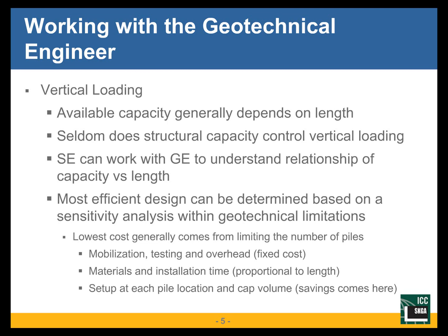We should realize that the cost in a pile foundation system comes from a number of different elements. First of all, you have the mobilization. That is, getting the pile contractor to the site, getting all their equipment there and set up. It's basically a fixed cost depending on how many rigs they're bringing to the site. And then you have the materials and the installation time. And of course, that's basically proportional to the total length of pile. And you have setup time at each pile and cap location, and also issues about cap volume.